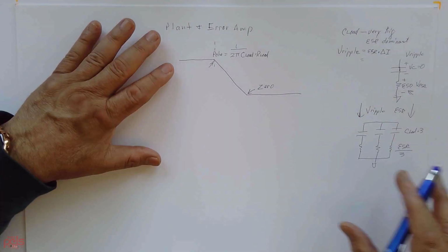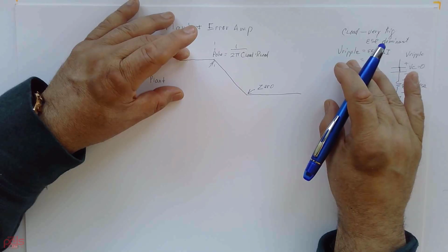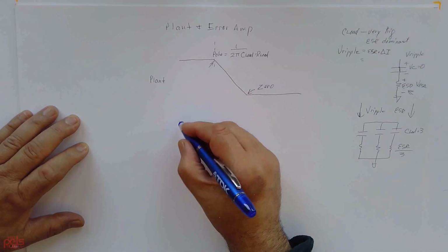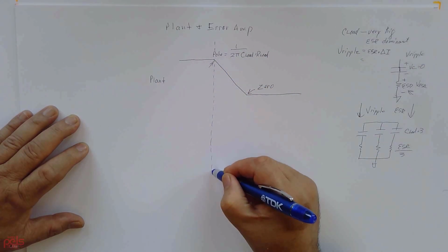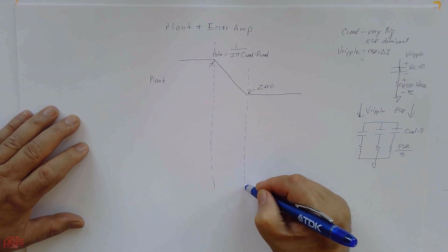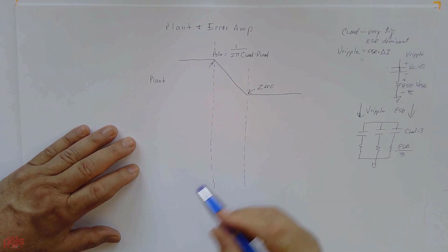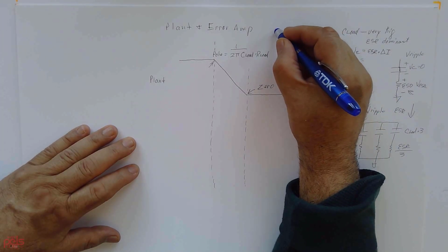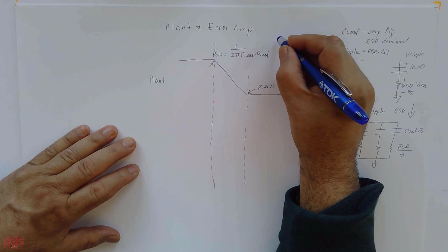So that's the point, that this is kind of fixed to satisfy your voltage ripple. What we can move or compensate, and just to make this a little easier, I'll draw points here. What Jack Alexander taught me was that if your filter has a pole, then you want to cancel it with a zero.